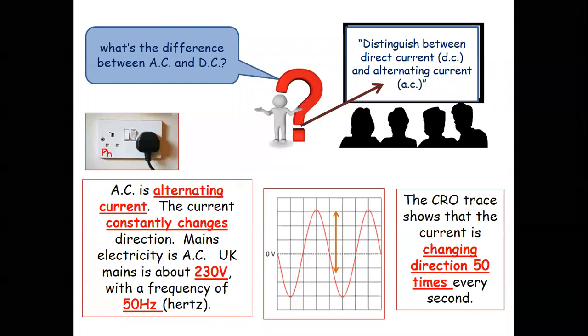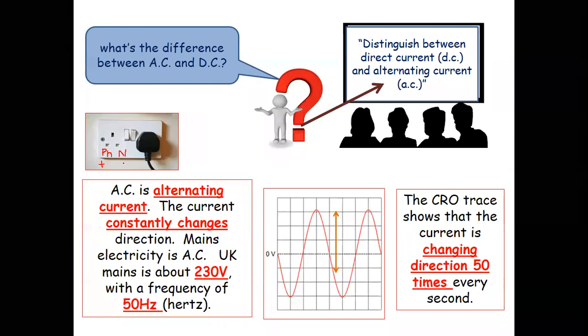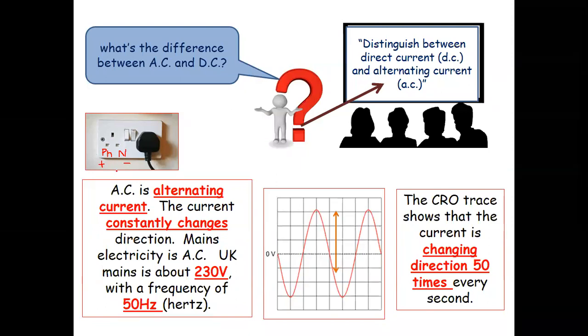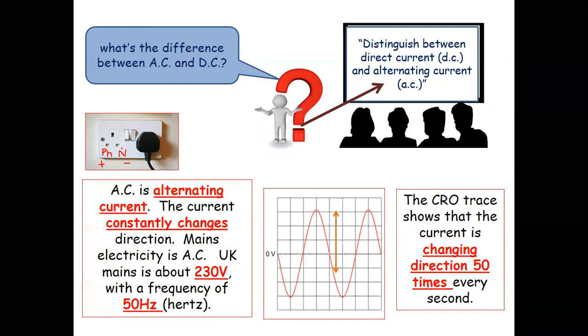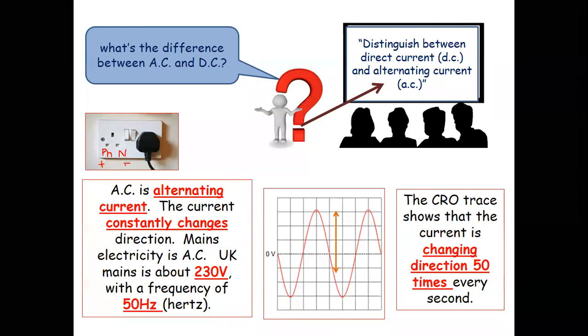In the same way, to get an AC supply, or single phase AC supply, we need a socket. One side of the socket is called the phase, and the other end of the socket is called neutral. The AC voltage is provided between phase and neutral. Remember, phase and neutral are not constant; they are continuously varying. So we cannot say that phase is always at higher potential with respect to neutral. But in DC, we can say one terminal is plus, one terminal is minus, and the positive terminal always has more voltage compared to the negative terminal.